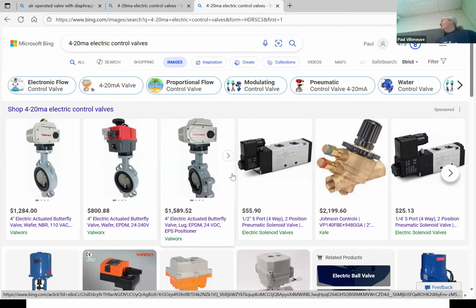So yes, with wireless, if it's terribly noisy, you can't run wireless, but you can do things with spread spectrum. You have much better radios and receivers that can work through a lot of noise. Obviously, if you're getting a lot of powerful spikes, that's harder. But that's why we run twisted shielded pair: as long as the emanating source is in a noise-clean environment, you can be spiking up and down all along, and as long as you set up the circuit correctly, you'll get no noise on your wires.